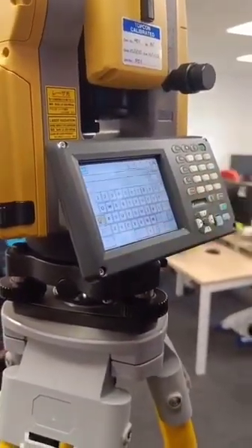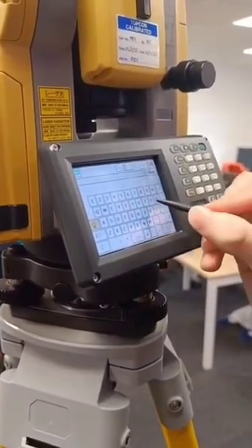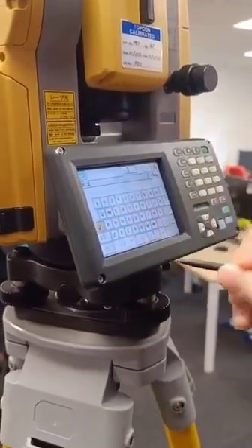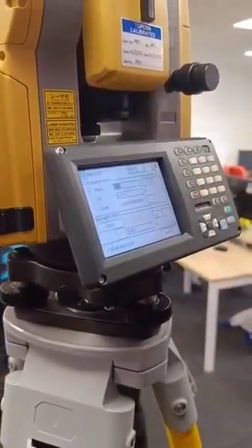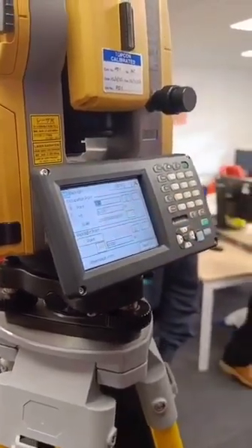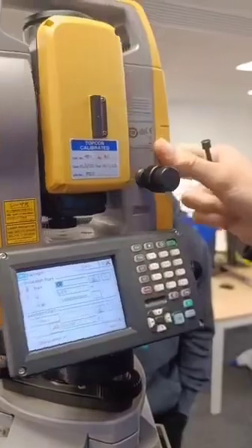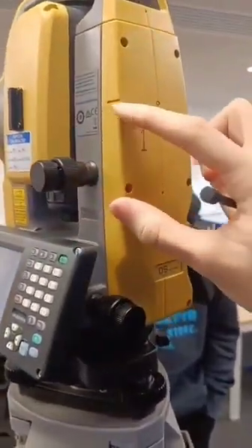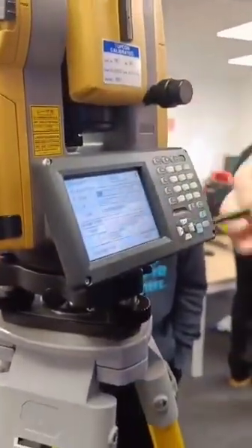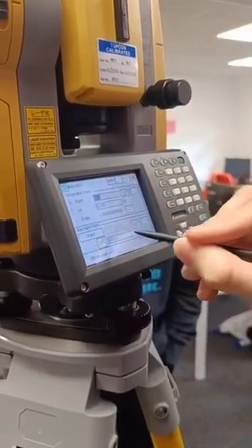So I'm just going to give it a name. It can be any name. I'm just going to put OC1 for occupation point 1. There's never going to be another one in your exam, but just for the sake of it. Height is just the height from the bottom up to, I believe, this line on the machine. I'll just turn it around. This thing here. So you take the measure and you measure that. You input it into height, and then you go to backside point.